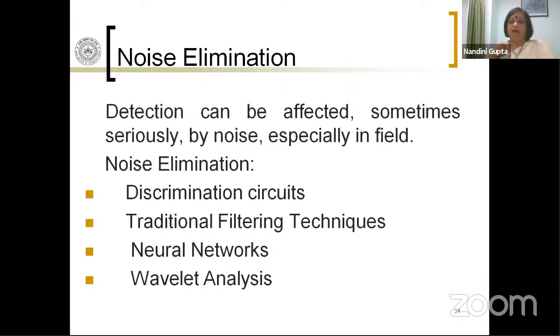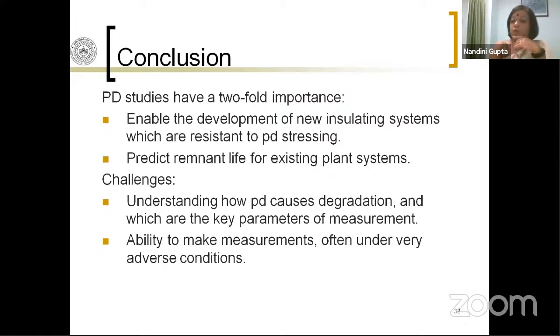In doing that, what we realized is that whatever energy is dissipated in a PD could also be detected. So if you have sound being emanated, you can try and detect sound, and detection through sound will help you detect and locate a PD. And therefore, we have a lot of literature and even commercial use of acoustic PD detection techniques. So it's not always enough to just be able to detect that PD is happening. We also need to be able to locate the PD.